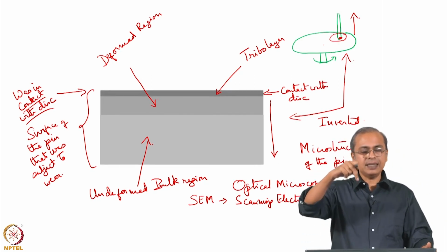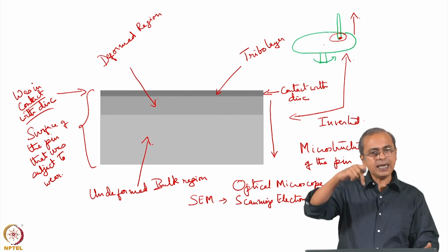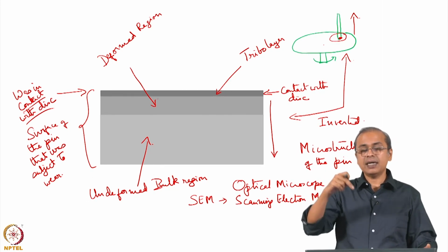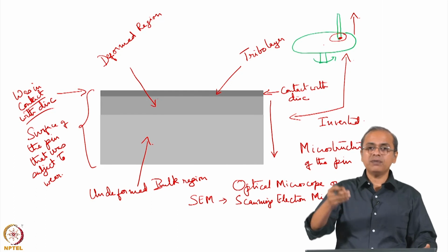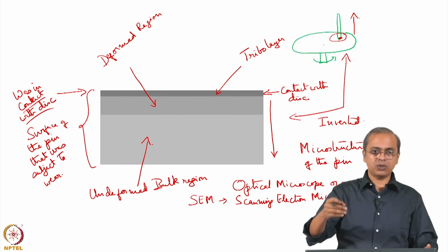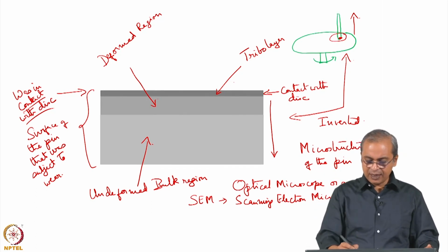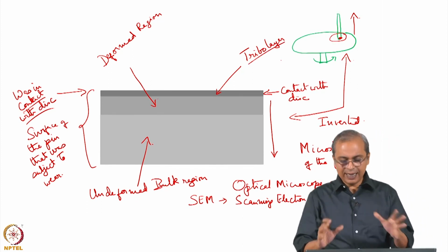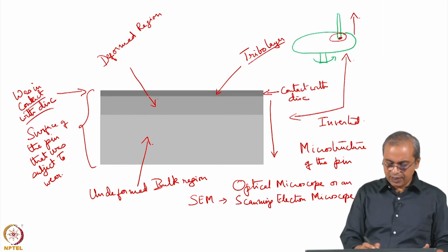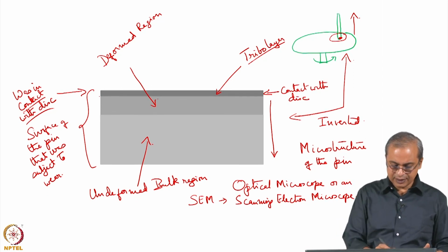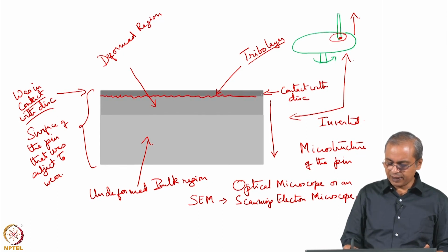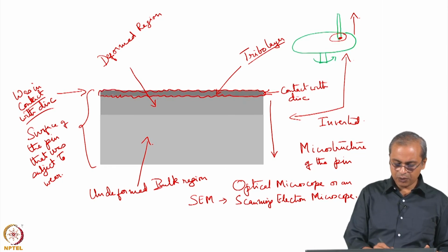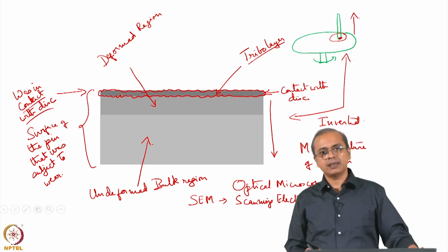The layer that is directly in contact, any kind of oxide layer it has, that oxide layer gets damaged, and then whatever is the exposed layer, that also gets oxidized. So you usually have sort of a damaged, debris-like layer which sits on the top. Even though I have shown it in this schematic as some kind of uniform layer, actually it will be a rough, somewhat damaged and uneven layer that you will see out here, and that is your tribo layer. This is called the tribo layer.